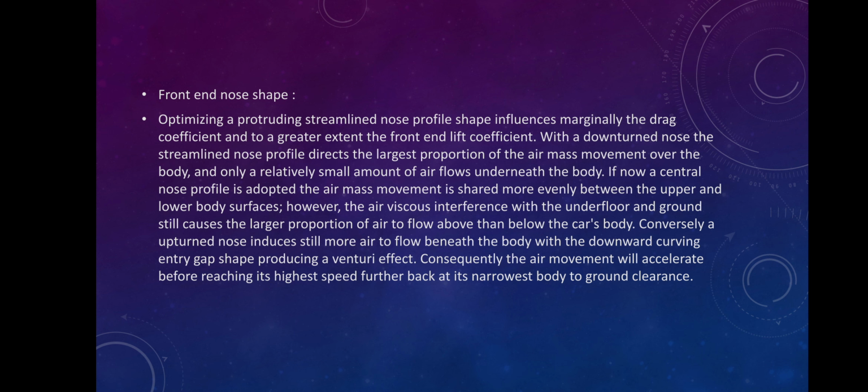If now a central nose profile is adopted, the air mass movement is shared more evenly between the upper and lower body surfaces. However, the viscous air interference with the underfloor and ground still causes a larger proportion of air to flow above than below the body.